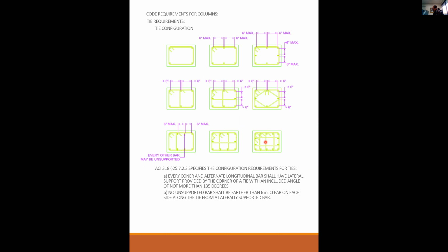And if you put a bunch of steel in the middle, it's very difficult to provide a confining tie situation to confine those in the middle. And the ties themselves have to have a rebar in the corner of the tie to make the tie effective. So hopefully that's a number of practical reasons why you hardly ever see steel in the middle.